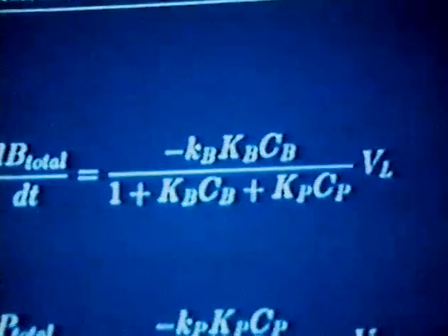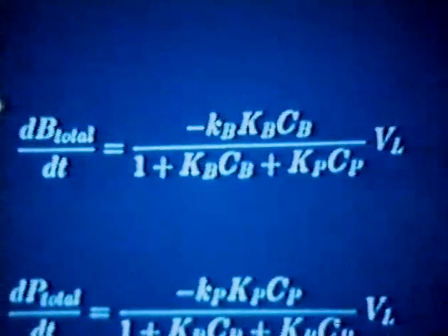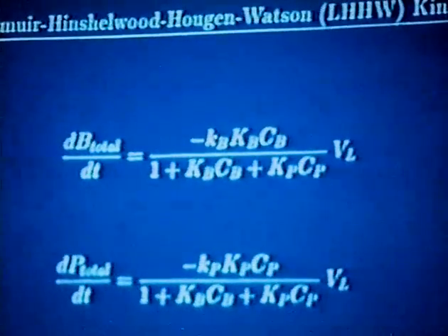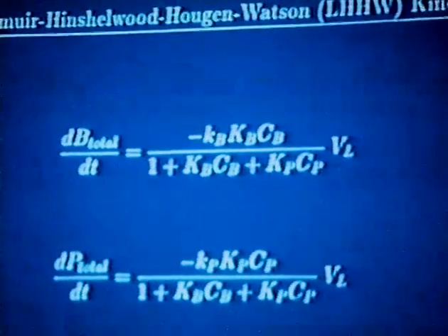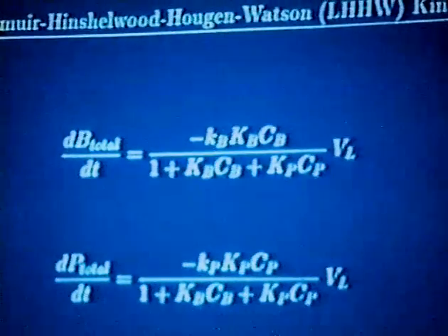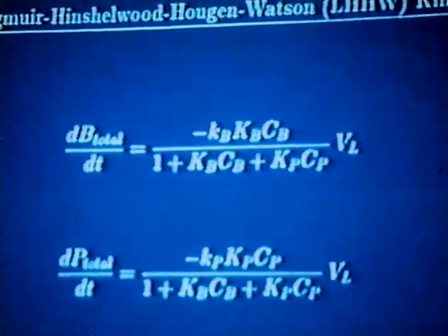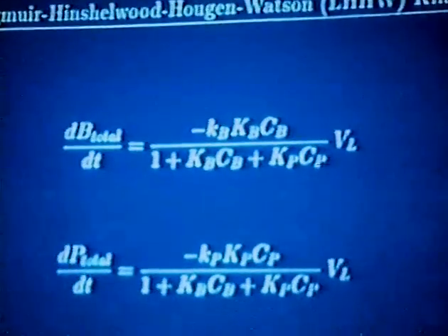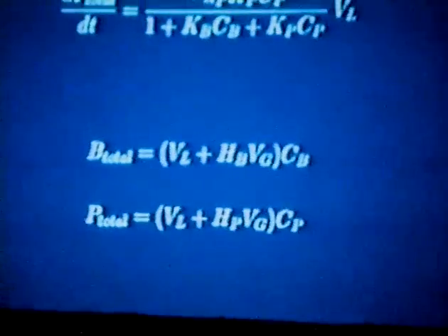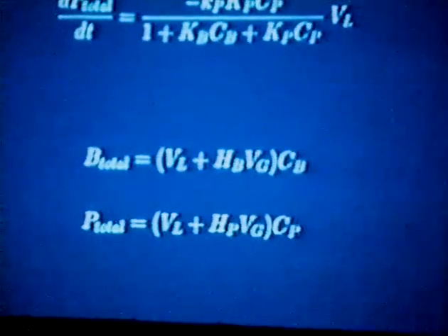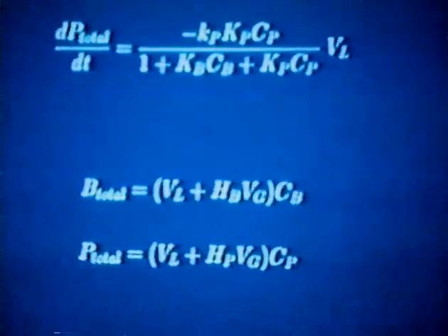The model we were using for the binary system is a Langmuir-Hinshelwood or Hougen-Watson rate law. We've made the modification now that the degradation is based in terms of the total amount of reactant in the system, because we have a headspace in the reactor, and these volatile organics will partition between the vapor and liquid phases. The correlation between those two phases was through Henry's law, which is entirely valid at the low concentrations we're working at. We assume then that the vapor and liquid were in constant equilibrium throughout the reaction.